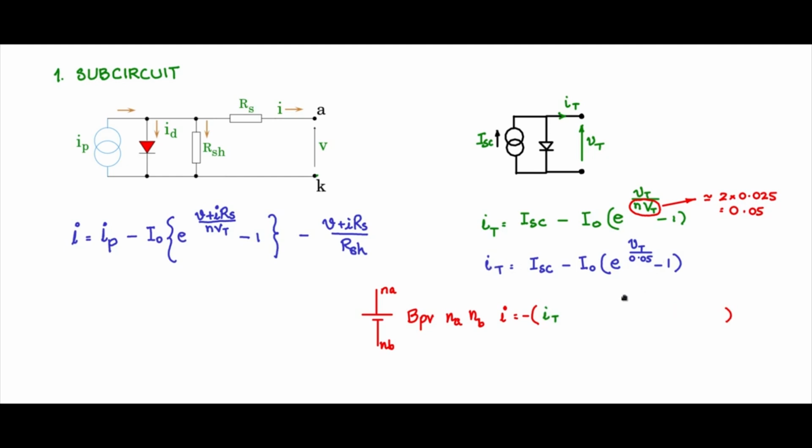We can introduce one more point at this stage of the modeling. We don't want negative current to sink into the PV cell. When IT goes negative, that is, reverses direction, we just want to not allow that. So set IT to 0 during those times.